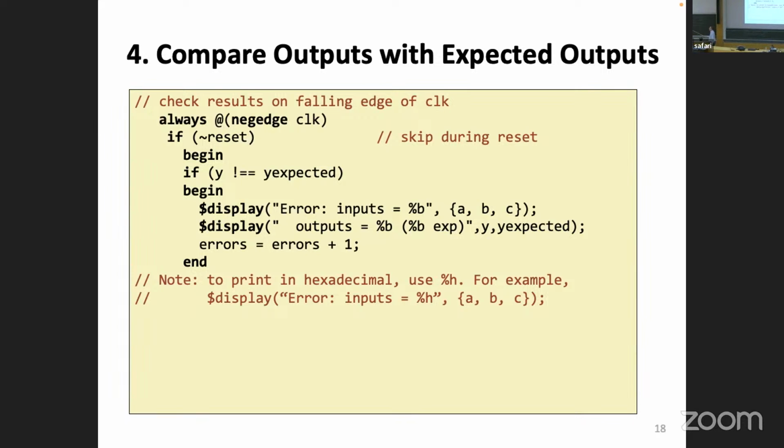We know that here we change the inputs. If it's a real circuit, there will be some propagation delay, and then I will have the outputs. Now, I could have checked for them at any point. It would have made sense to check them as late as possible. There was a good reason why we gave them this period, because we realized that this circuit needs this time to calculate its outputs. However, I can run the simulation at a slower rate, so it's not a problem.